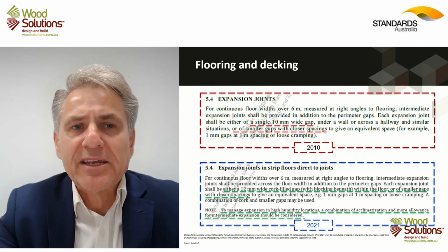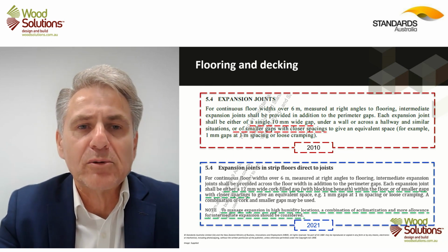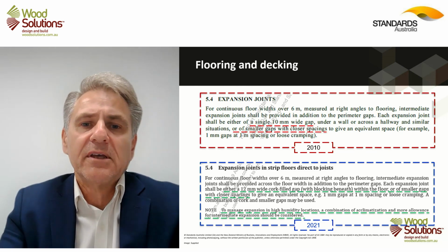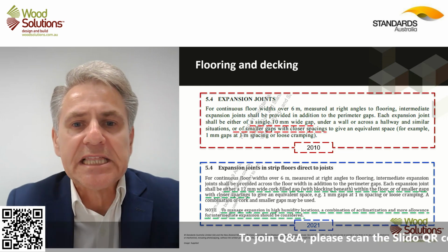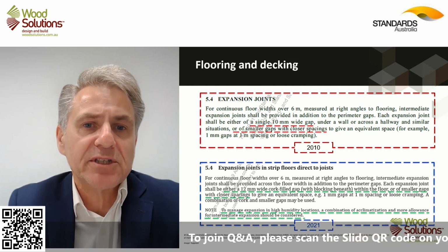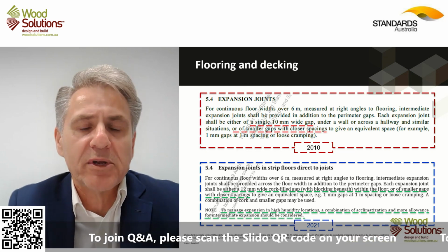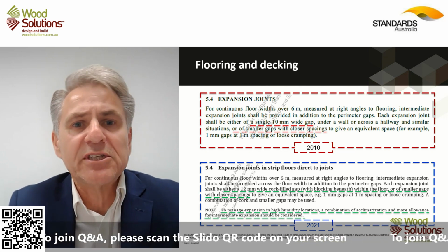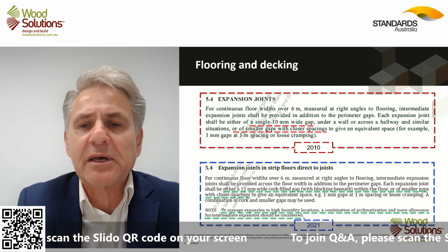But it does talk about potentially looking at the gaps and how many you need. You've got to also take into account the environment where that floor is going to be laid. And it's just a note. So just in relation to standards, notes aren't mandatory, they're informative. It's just trying to give you some additional information that depending on where you're going to be laying your floor, you may need to consider some other things.